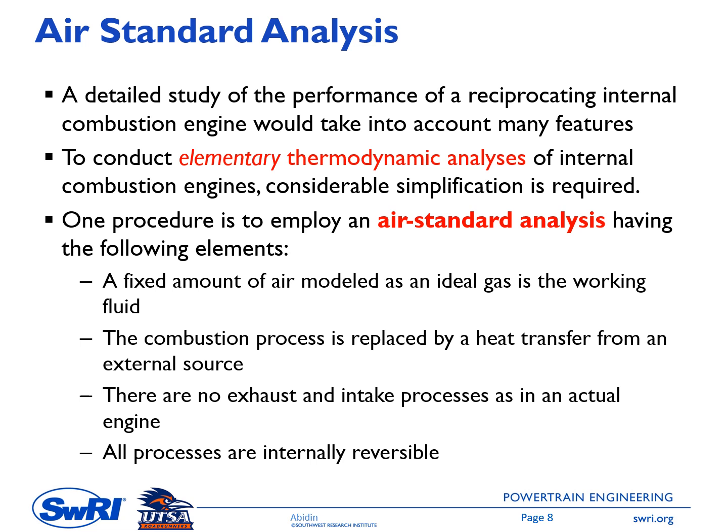Rather, we'll assume there will be a Q in entering the internal combustion engine. And then there are no exhaust and intake processes as in an actual engine. So we'll assume that the intake process and exhaust process occur in a simplified way. And the last one is that all processes are internally reversible, which means sigma equals 0.